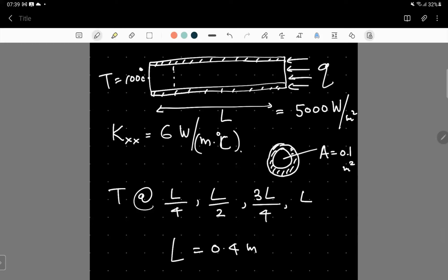So now we can use the stiffness matrices which we derived previously. Since this is governed by the conduction, we only have the conduction term coming into play. The convection term is set to 0 because there is no heat transfer by convection from the surfaces, because the surfaces are insulated at the perimeter.